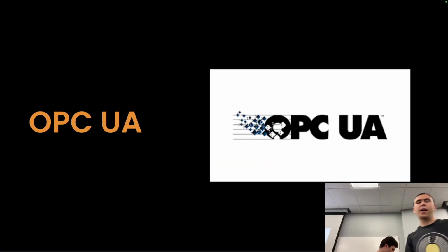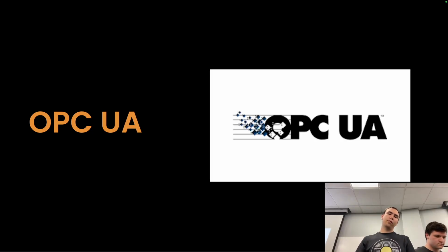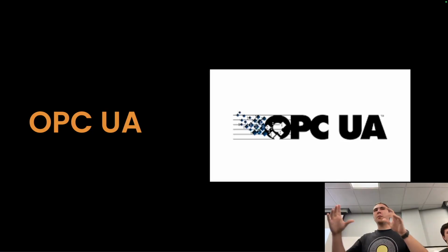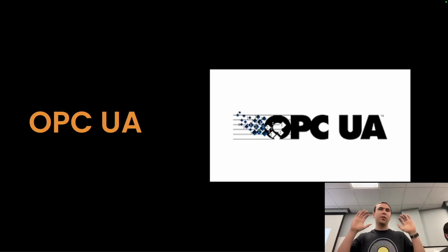Yeah. So now for our last protocol, and kind of most complicated, but only because OPC UA is not actually a protocol. It's a standard. So like PROFINET was a standard with some protocols underneath it, but it still had its protocol. And then you had the IEC 61850, which is a standard, but it also had a bunch of protocols that were actually defined in it.